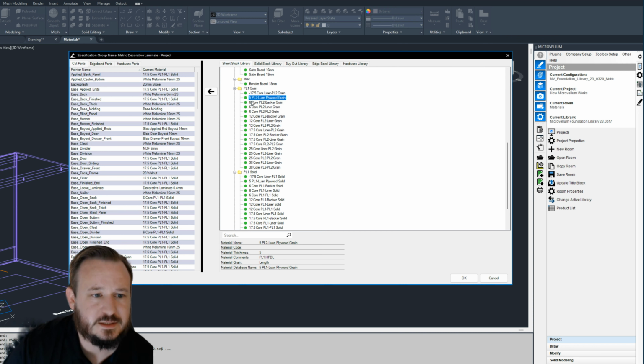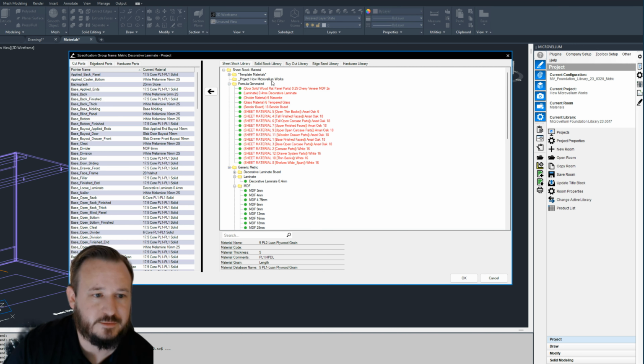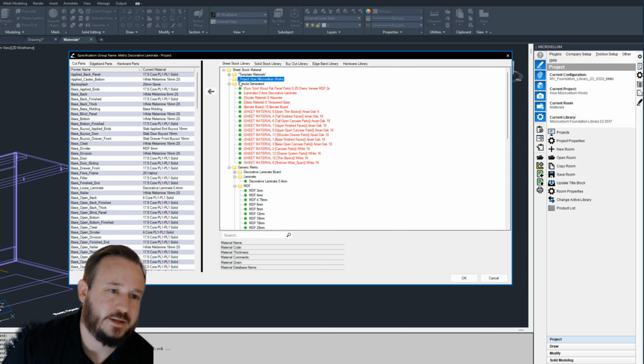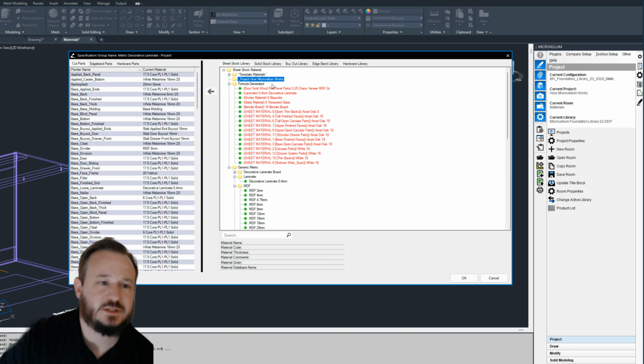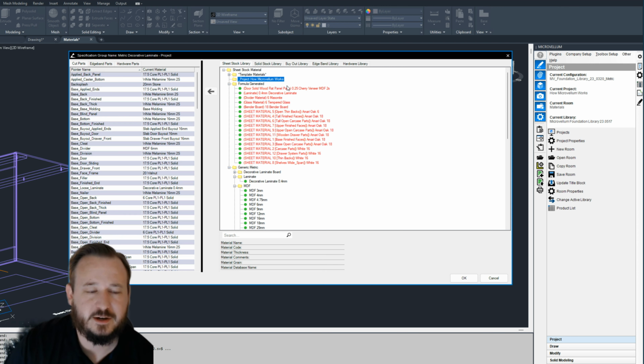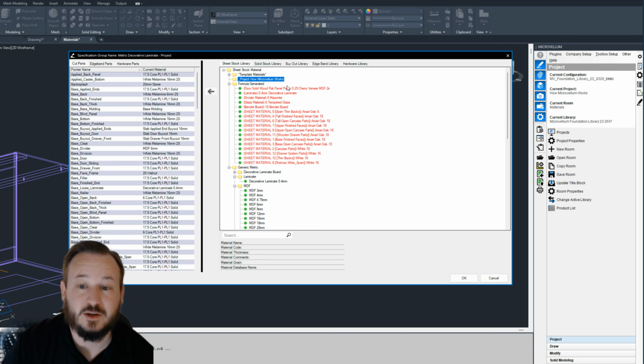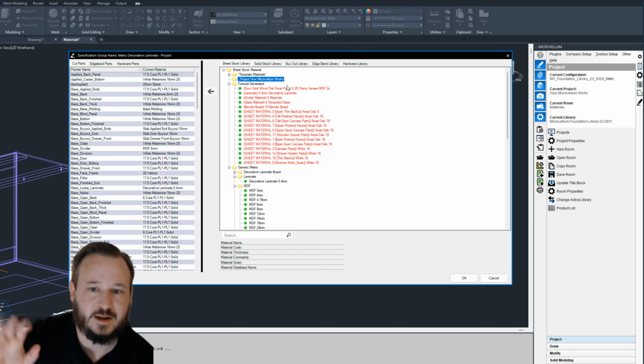Now, if I needed to edit anything else besides the name or the description for this material, because this is a library level material, not clonable, my only option is to copy this to the project level. So every material file in a project has this folder that is _project and then the name of your project. So I've got a project called How Microvellum Works, and this folder is that. And so when we talk about project level materials, those are materials that have been copied to the project level and are fully editable in that project, and they only exist in that project, not in our template.